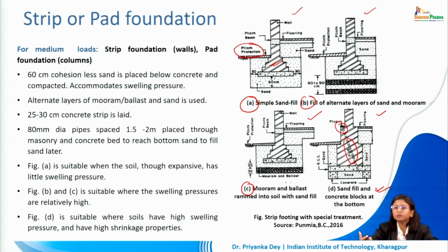So during the long life of the building, if the sand shifts underneath this concrete base due to the swelling action and the shrinkage action that is happening seasonally, we can keep adding sand even in the later years for our foundation to keep functioning properly, given the special and unique characteristics of the black cotton soil.